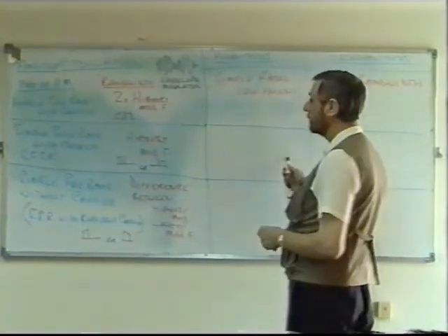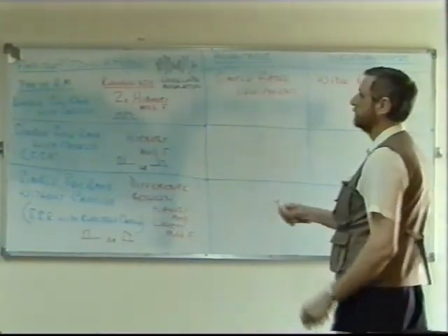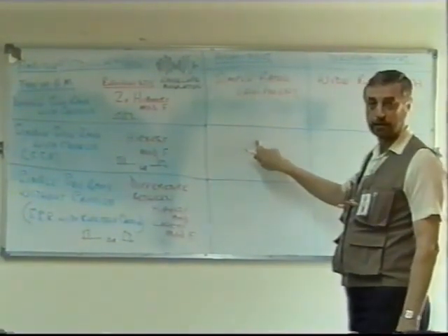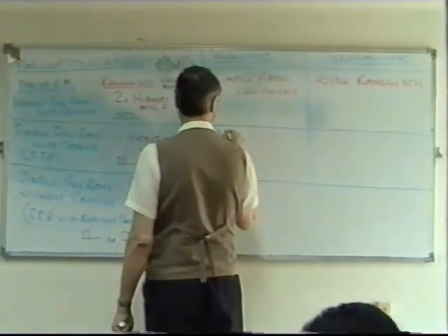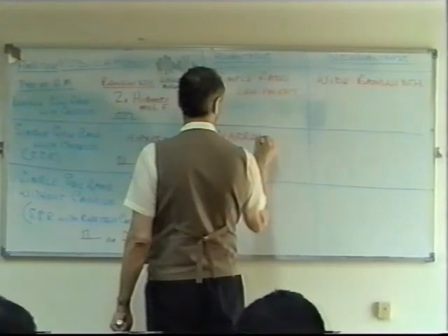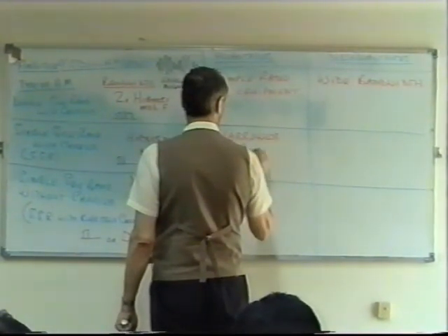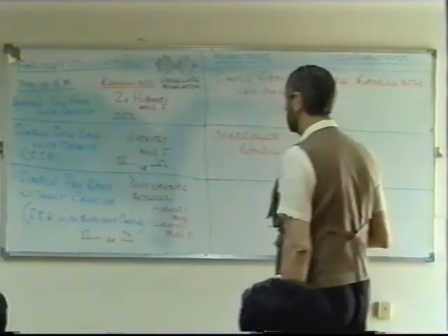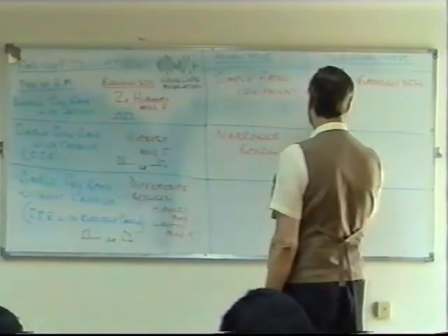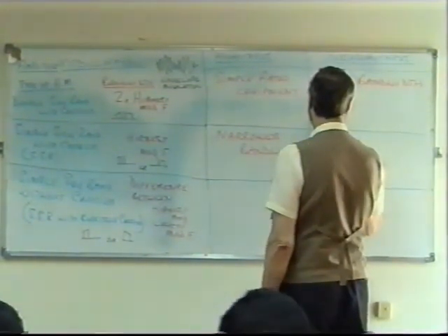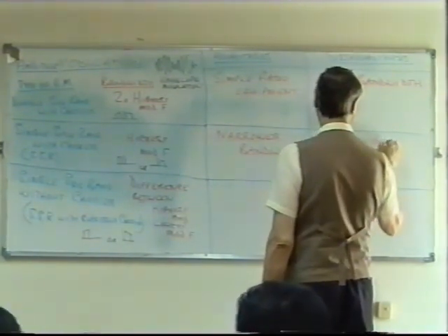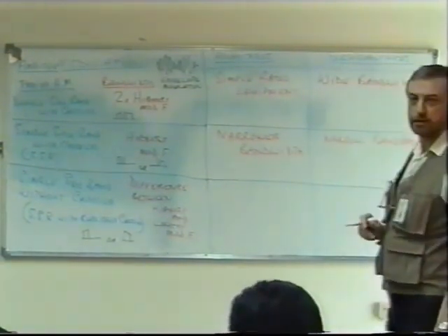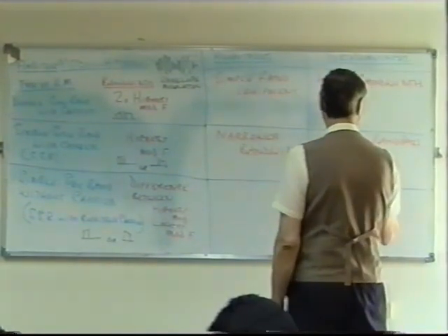Okay, and when we consider, of course, single sideband, SSB, then the main advantage is saving on bandwidth, isn't it? Narrower bandwidth. So that's its big advantage. And that's for the same amount of information. We're not losing any information there. Disadvantage, well, you need narrow bandpass filters. Now that might not seem much of a disadvantage, but again, we've got to go back to early radio sets to see that this was a difficult thing to achieve in practice. Narrow bandpass filters.